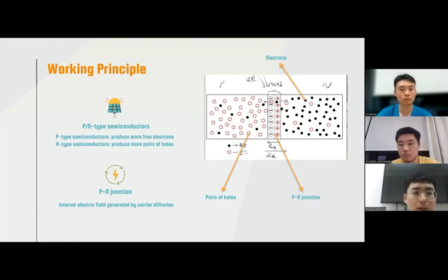When the p-n junction is irradiated by sunlight, the semiconductor is affected by the change of illumination and temperature, and the two kinds of charge carriers will be excited respectively. Because of the built-in electric field, electrons move to the n-type semiconductor and holes move to the p-type semiconductor. A potential difference is gradually created between the two semiconductors. P and N are connected through a wire, and an electric current is generated. This is the simplest introduction of traditional solar cells.